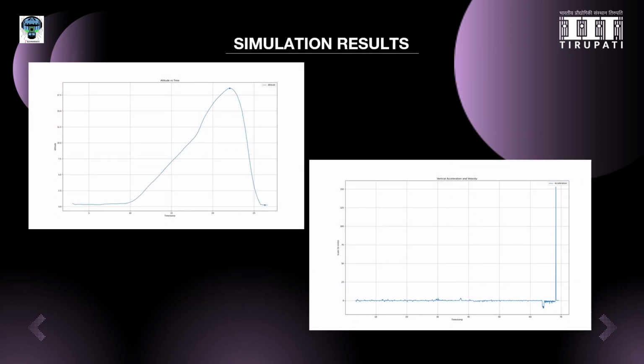Our system in simulation. We used a special motor failure induction command to deliberately cut power to one rotor during flight, simulating a sudden failure. The drone sensors and this control software then took over automatically. In the test, after the failure is triggered, the drone enters emergency landing mode. The custom controllers pitch the drone slightly and throttle down to descend gently.